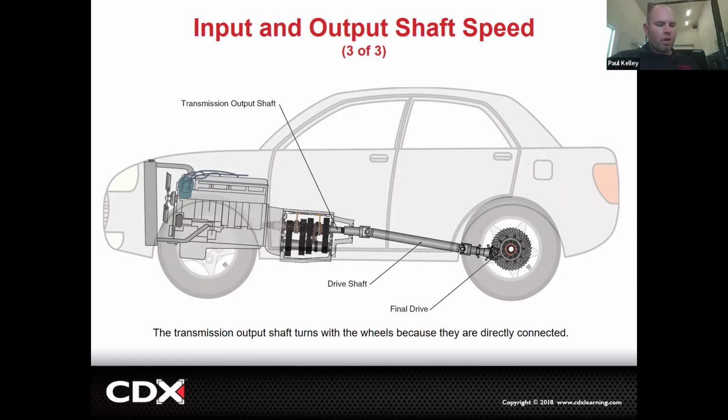You could do that, but they do have cars from the factory where you might have to engage it in a menu, but if you push the clutch pedal down, there's a clutch pedal switch, and that switch will give a signal to the engine control module, the ECM, and it'll actually momentarily kill the spark or kill the fuel, probably the fuel. At which point your clutch is still engaged, but the engine power is off because they killed the fuel injectors, not the fuel pump. The fuel pump would take a while to die. If you kill injectors, boom, that engine's not making power right then and there. They could even kill injector and fuel. Then at that point, you can actually do the shift.